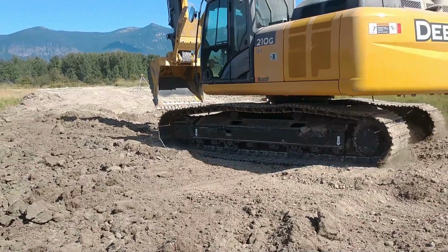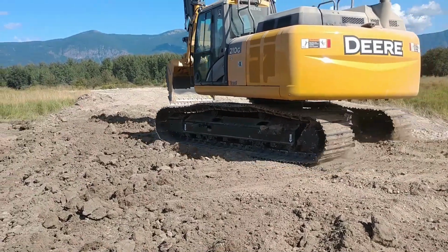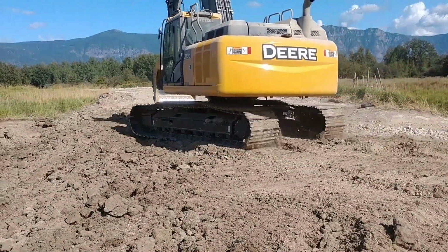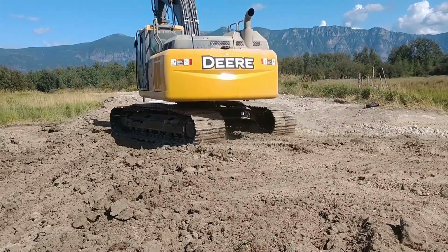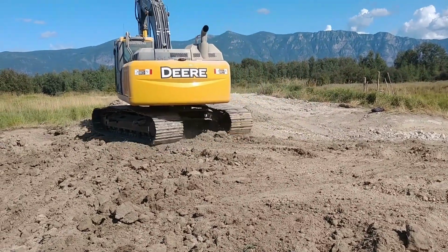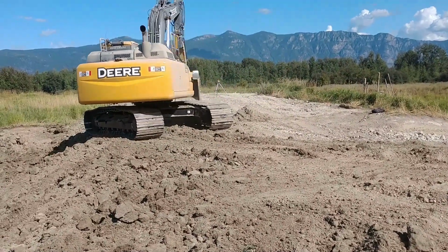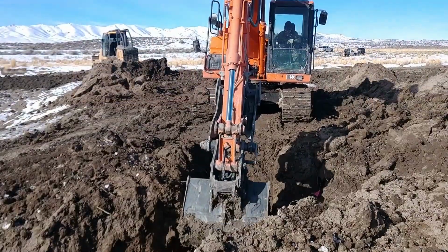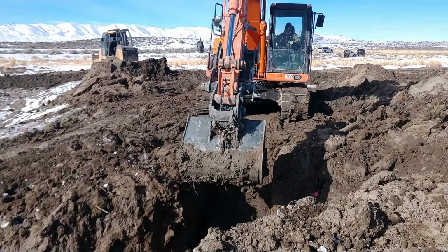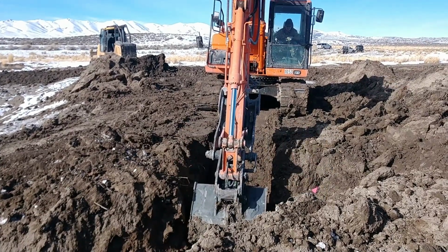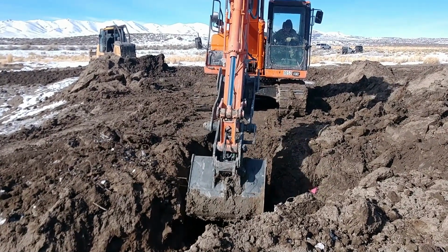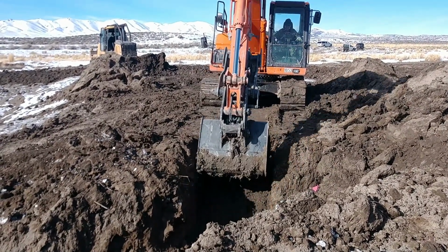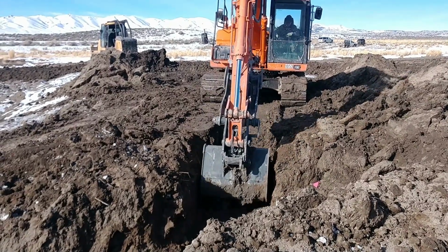We're watching an excavator operator compact clay texture soil in a trench to form a groundwater dam. Layers of soil, only 6 inches thick, are being placed in the trench, with each layer being compacted by the excavator. Here the operator is using the bucket on the excavator to compact the soil being placed in the trench. He's being careful to make sure that all the soil placed in the trench is compacted before adding another layer on top.